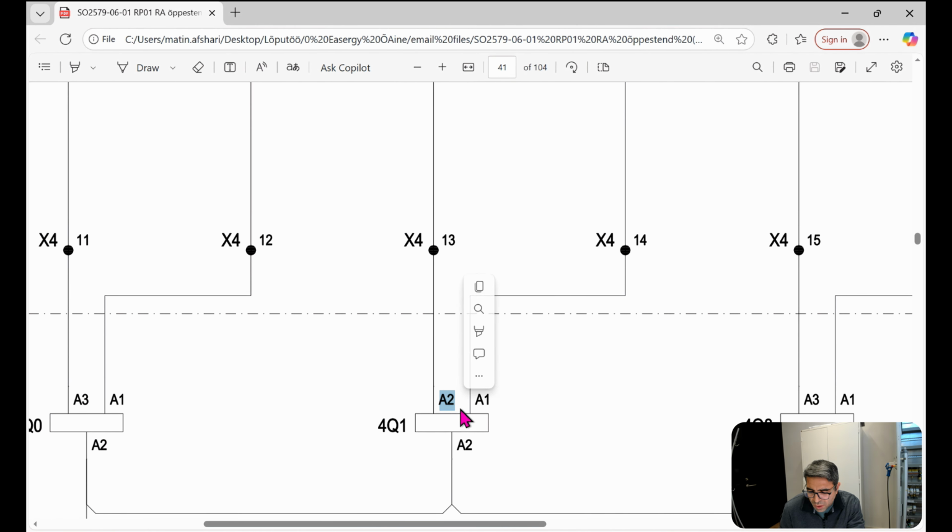Anytime that a fault happens and the relay acts, does tripping, this connection that is DO4, this one, usually normally open, will be connected. And we have to connect these two sides to the tester feedback, and when this is connected, the tester will detect that the trip has happened.